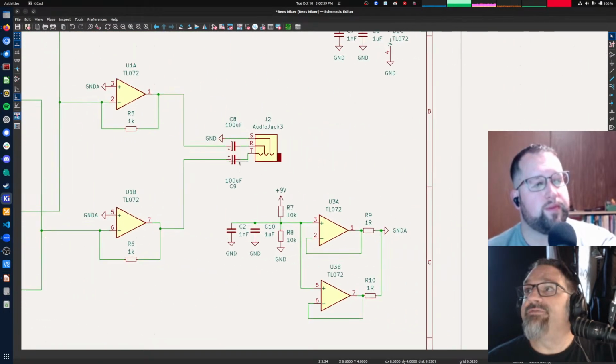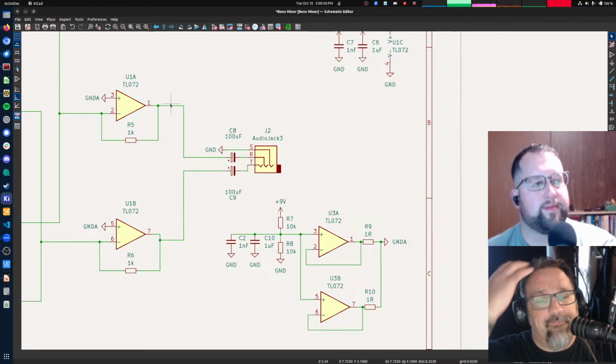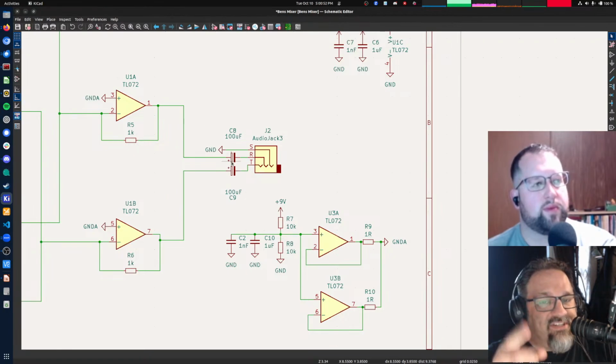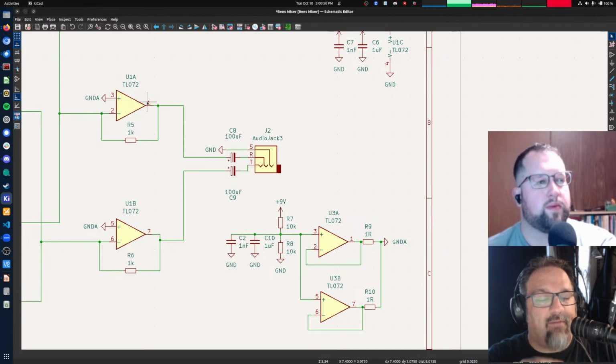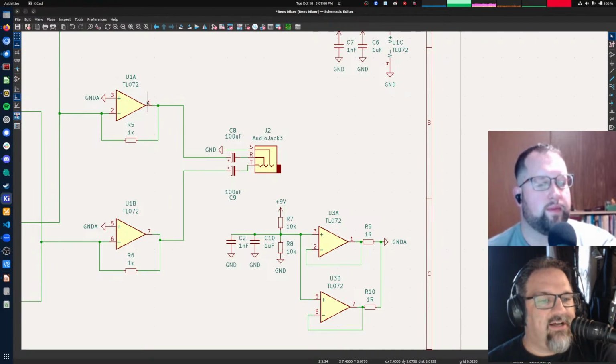Although, I just realized that was underneath the thing. We could get rid of these DC blocking capacitors because this will be putting out a signal above and below actual ground at that point. Having said that, it's generally a good idea to leave those capacitors there anyway because op amps will always put out just a little tiny bit of DC voltage. It's their common mode.